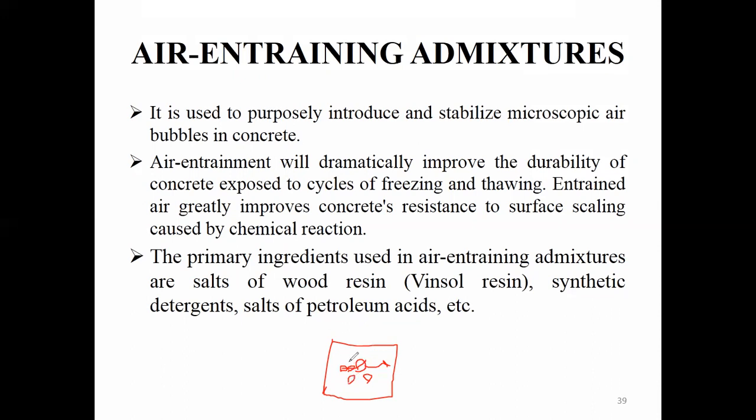Since these pores are interconnected, the water or the chemicals, which are not good for the concrete, may cause sulfate attack, chloride attack, or alkali aggregate reaction in the concrete. These are all not good effects on the concrete. It will make the concrete get affected. So we have to reduce this entrapped air. This entrapped air is not at all good for concrete. For that purpose, we will be doing compaction. This we all know very well.